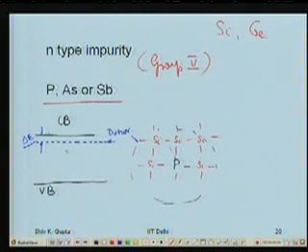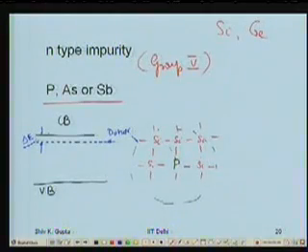So where does the Fermi level lie now? Yes, I'll come to that. At 0 Kelvin, the Fermi level is close by to the energy level of the different color, here. And as the temperature rises, this goes down and comes to the middle of the band gap by the time it reaches high temperatures. It's a function of temperature, this Fermi level. The Fermi level at 0 Kelvin is close by this, and then it goes on decreasing, goes to the middle.